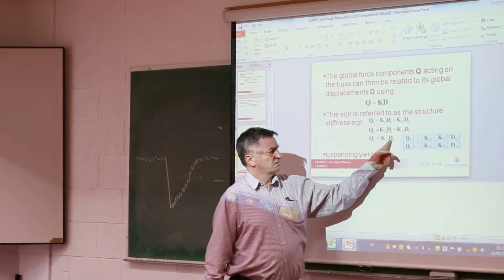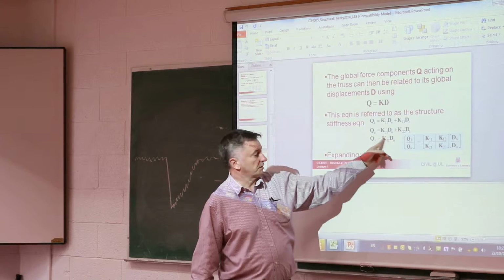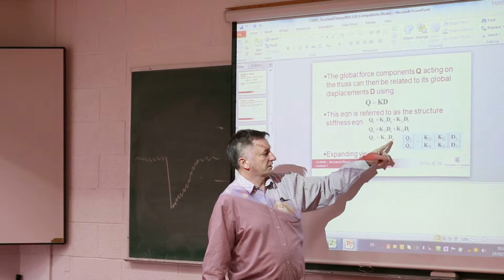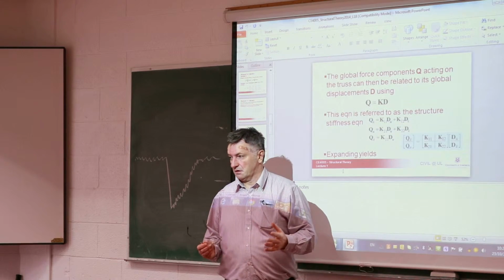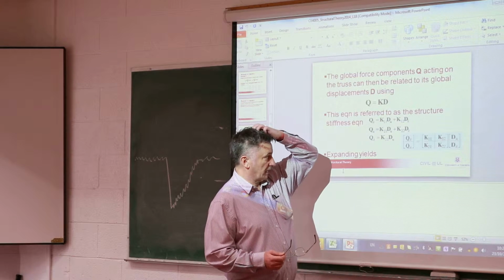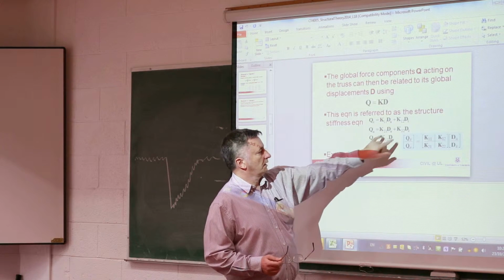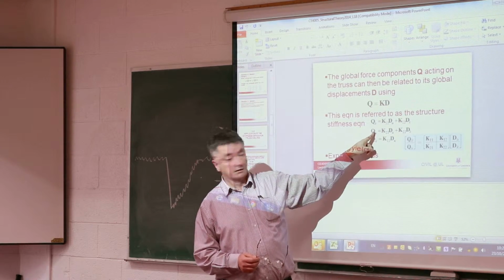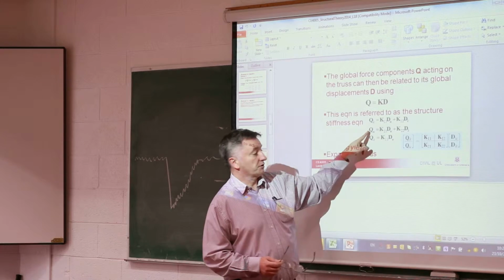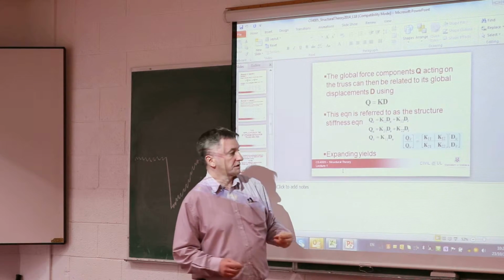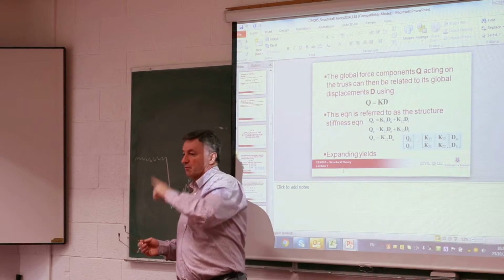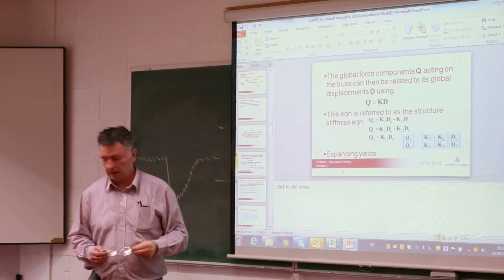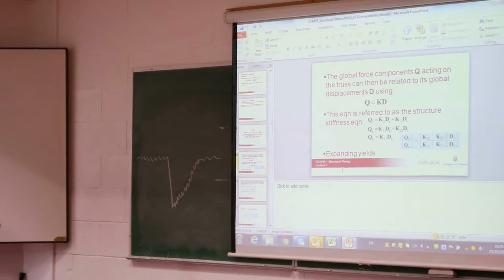And there's actually a couple of YouTube videos on Gauss-Jordan elimination. And once you've solved that, you now know what all the displacements are in the structure. And once you know that, you can now work out what the unknown reactions are. Because now you know that and that. So now you know all the reactions, all the nodal forces, and you now also can go back to the element stiffness matrices, and you can calculate what's going on with the element.